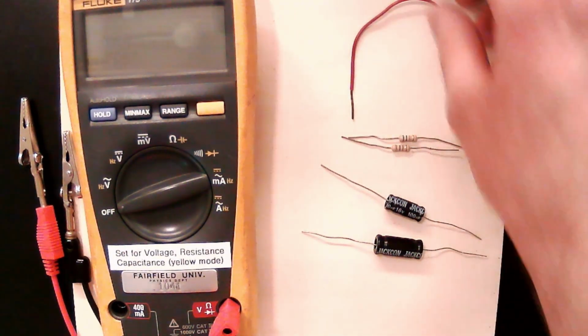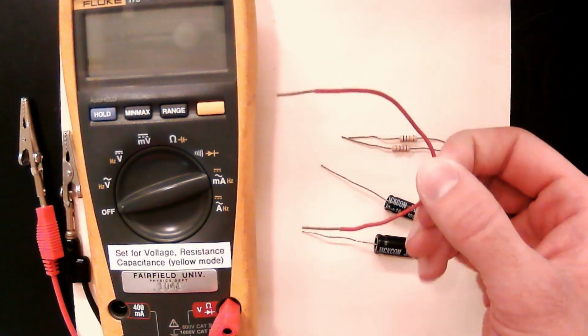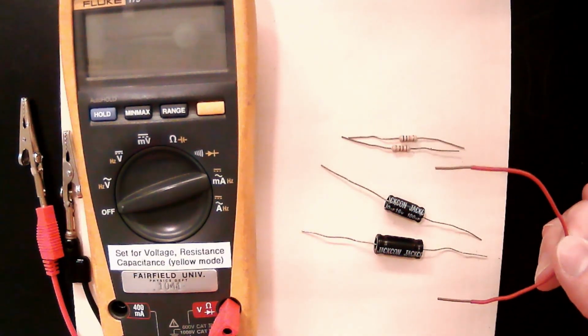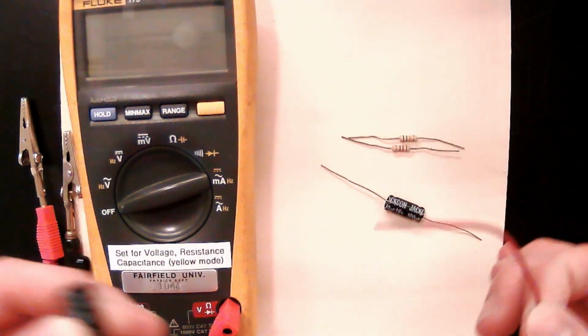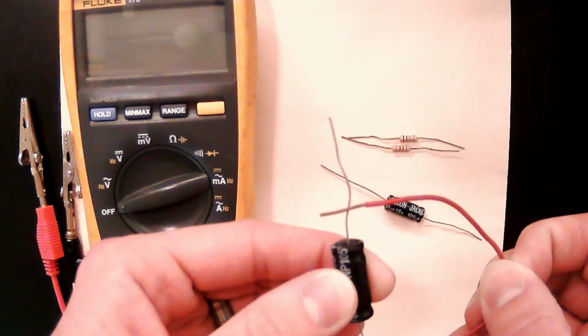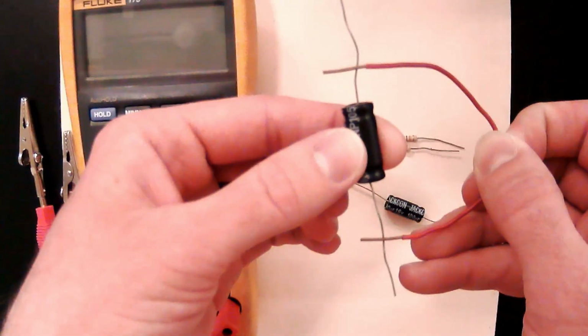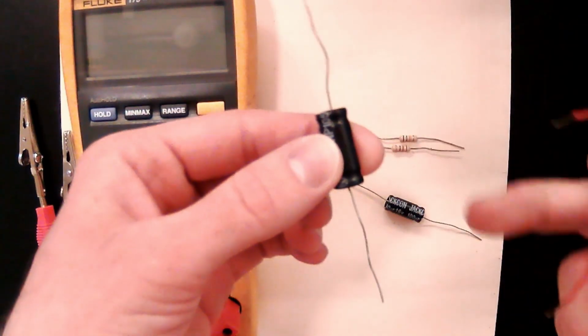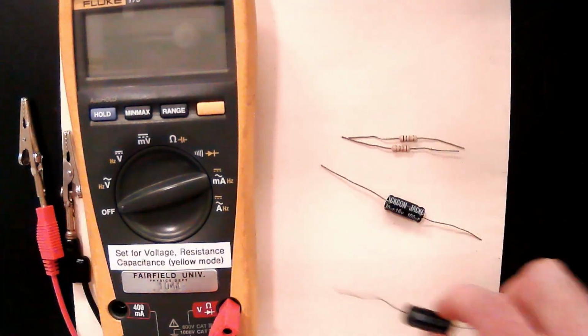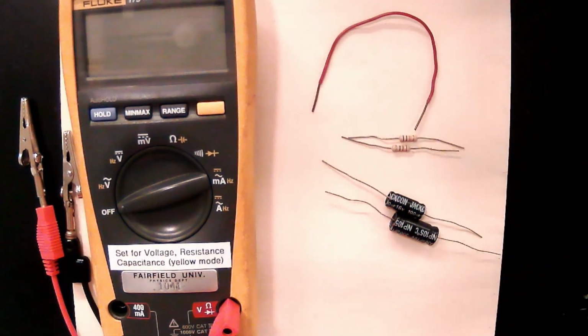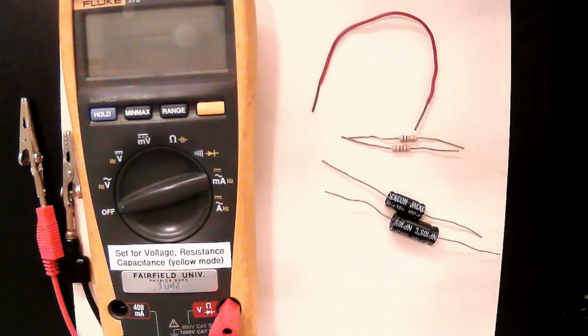You also have this red wire here, which is essentially a wire with no resistance, right? So effectively no resistance. If you were to touch it on either side of the capacitor like this, you will discharge any charge that is currently built up in the capacitor, setting the voltage effectively back to 0, which you will do mostly in experiment 2.